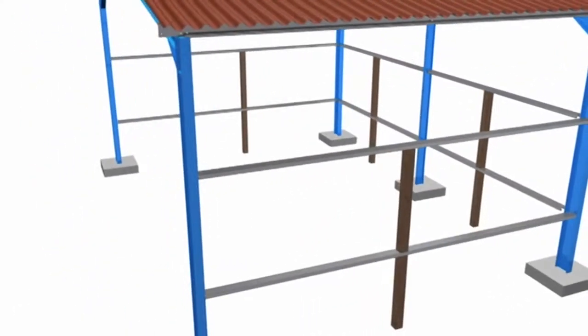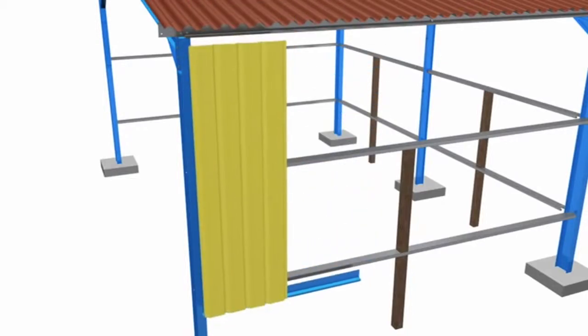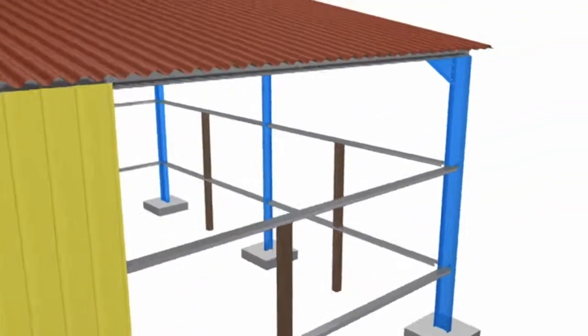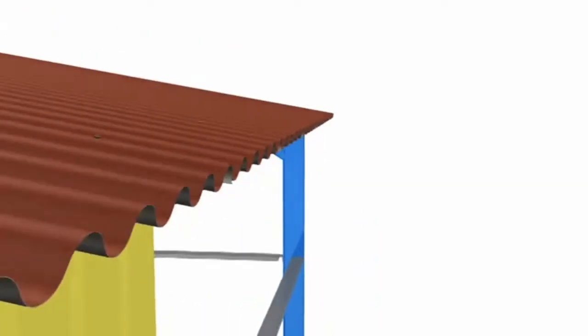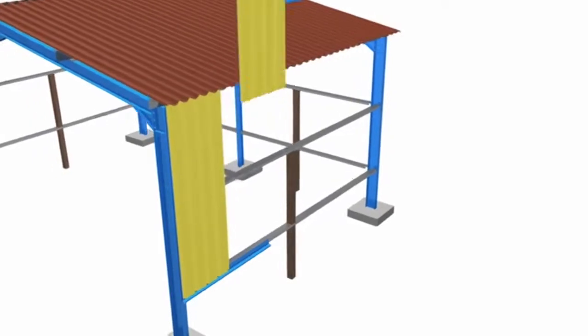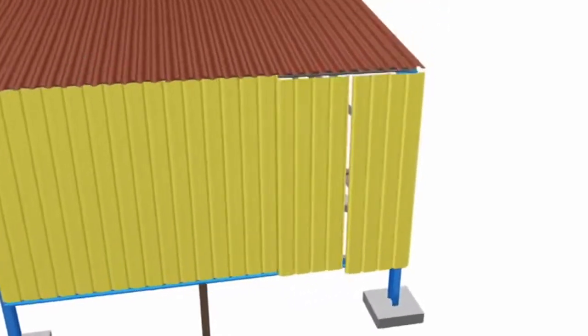as well as the MX and the NX corresponding figures. Once these calculations had been completed, we can then design the column for one case and then cross-reference it with the other. In order to choose the design member which is under axial compression, it was required the L buckling to be calculated first.